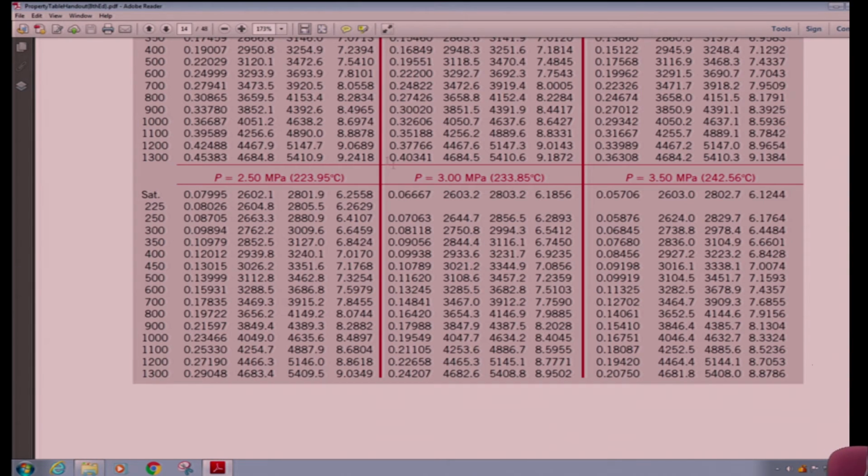So you would have to go in here at saturation, which now corresponds to 242, right? These are your saturation conditions. These are your conditions at 250. So you're interpolating between, let's say, 242 and 250. That's why I said 225 wouldn't happen, because 225 already puts you into the two-phase region. But let's say the temperature was 245. So 250 obviously isn't right. The data at 242.56 is not right either. You're in between the two. So you would just do the interpolation between those two entries.